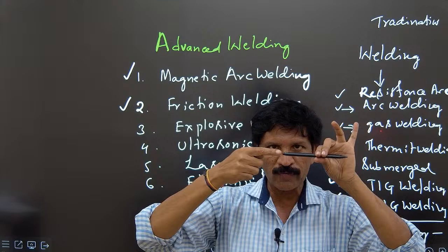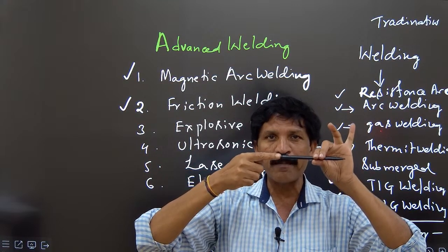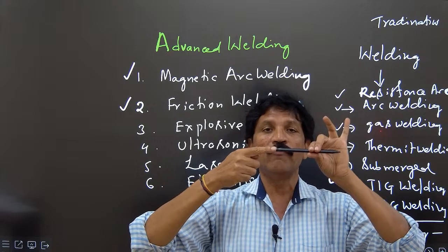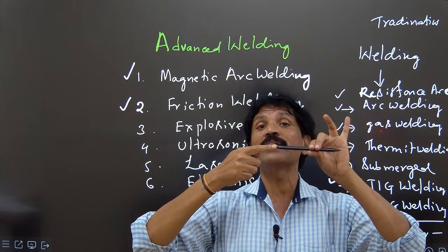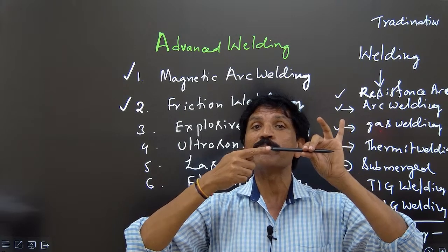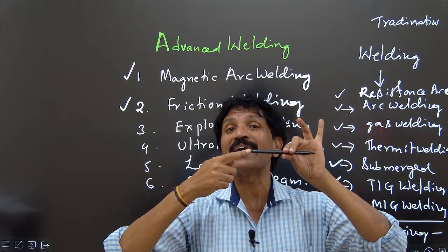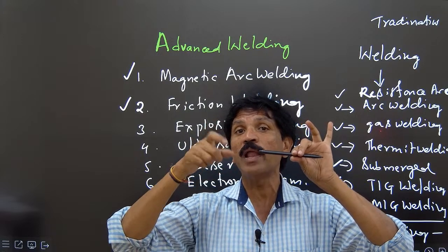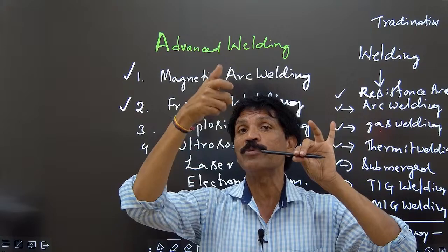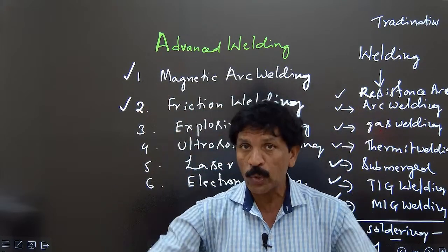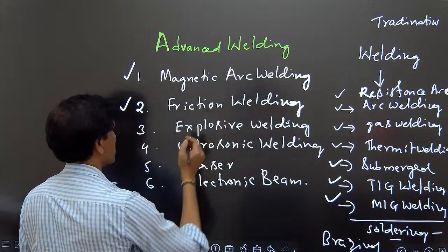When these two faces meet each other, a lot of temperature is generated due to the friction. Whenever the temperature is raised, definitely that leads to melting of the base metal. Whenever the metal melts at its faces, automatically the ion exchange is possible and the weld bead is generated on each face, so that the metals will be joined together. So that is about friction welding.